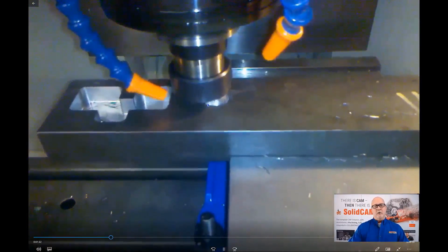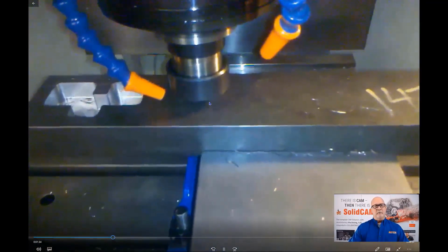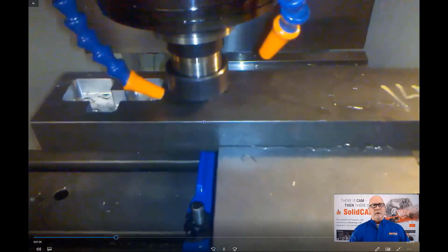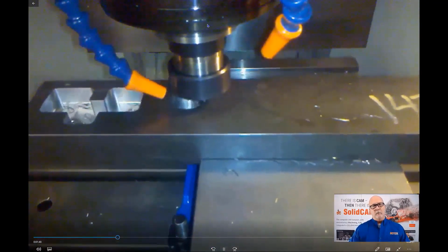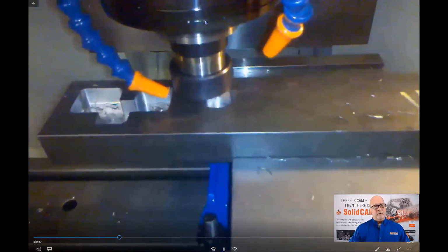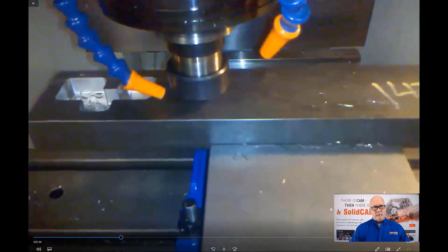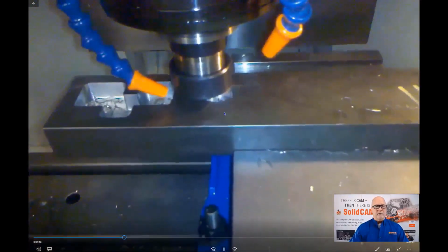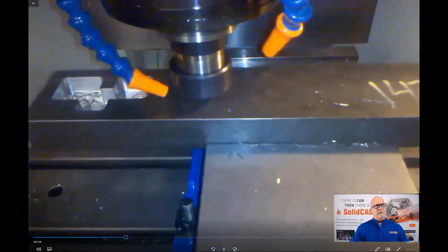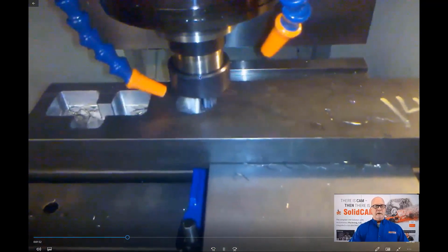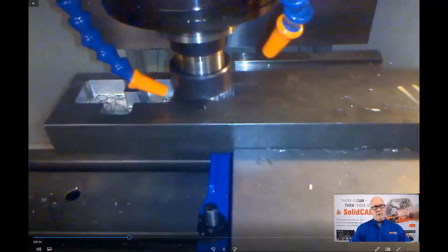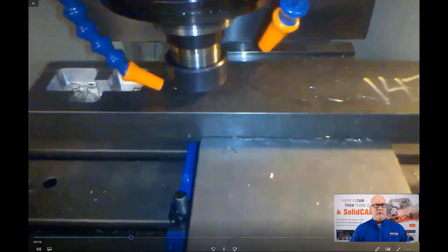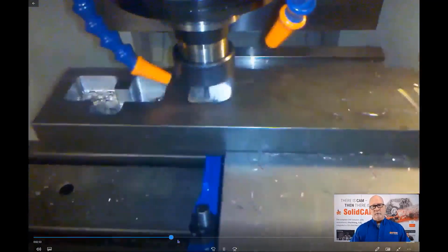Notice I'm cutting all the way at full depth, 1 inch depth of cut on a 3/8 inch end mill. That's greater than 2 times the diameter. Again, we only have a 4,000 or 4,500 RPM spindle, but I'm using all 4,500 RPM. This machine will only give us 50 inches a minute travel before it starts hesitating. You can actually see it hesitating just a little bit in here. I'm pushing the limit of that. Okay, but let's go ahead and advance this forward.